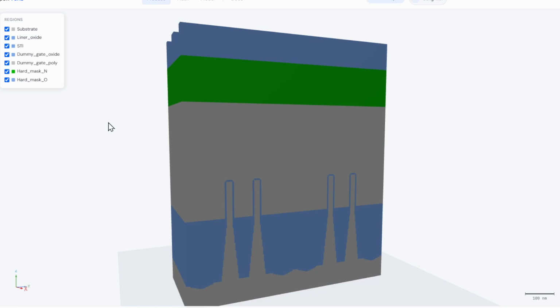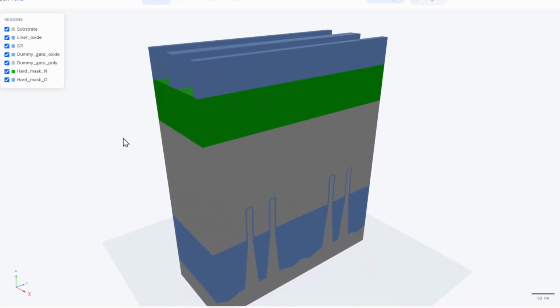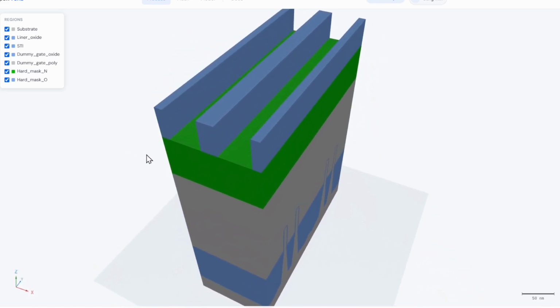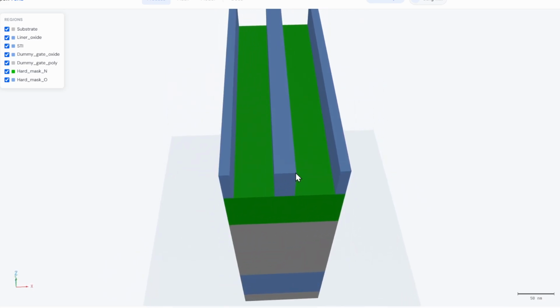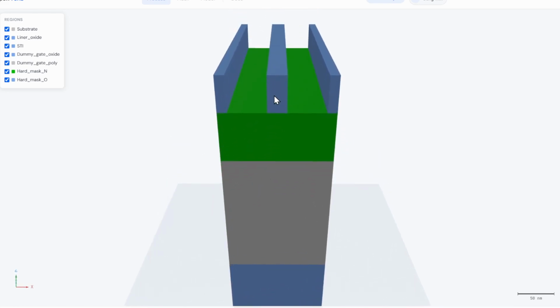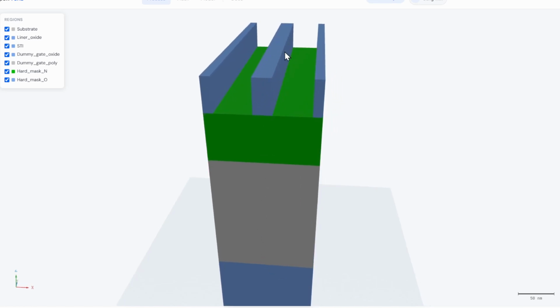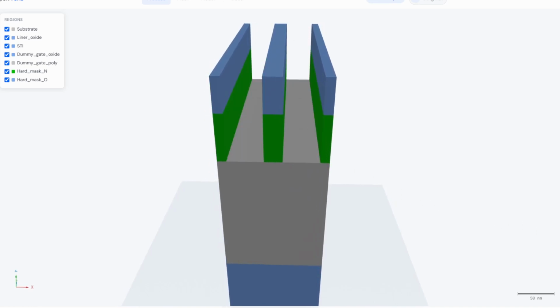Using the mask pattern, we have etched away first the top silicon dioxide hard mask. So as you can see here, that is etched away, and this is corresponding to our pattern for the full dummy gate, and this is a half one. And of course, we wanted to transfer it to this polysilicon layer. Right now, only the top hard mask is patterned.